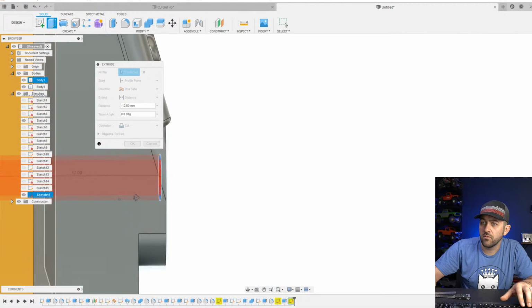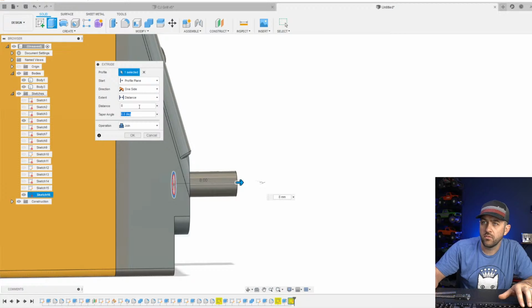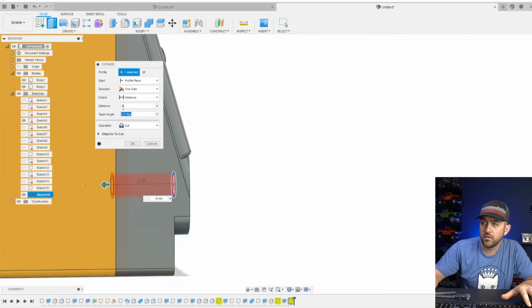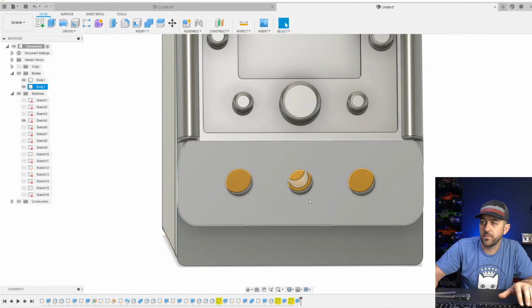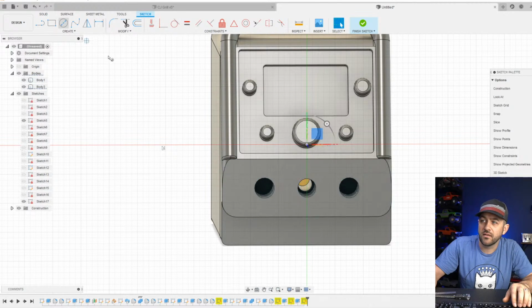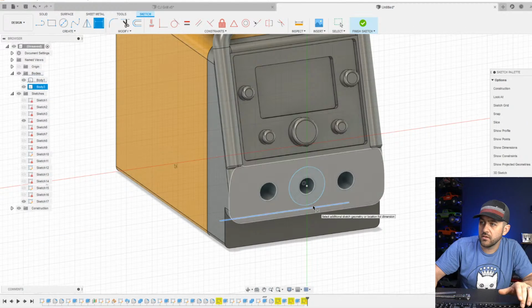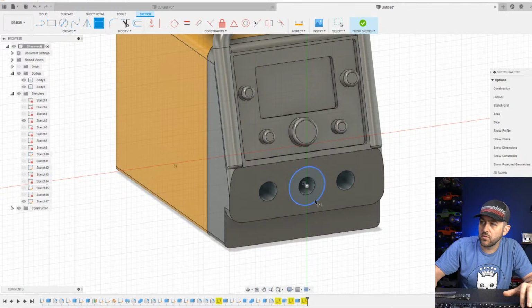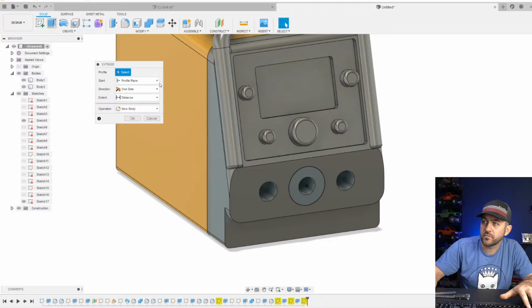And we'll go in, was it 8 millimeters? Yeah. So, oops, not positive 8. We need to go negative 8 as a cut. So now you're going to be able to take a 3 millimeter screw. I'd probably use a button head. Let's clean it up even a little bit more. Let's countersink it. Let's go with a 7 millimeter countersink. That's 4 millimeters deep.